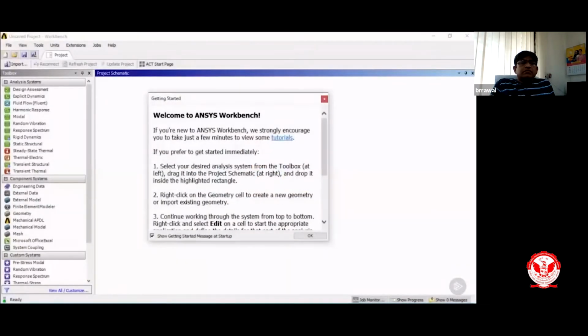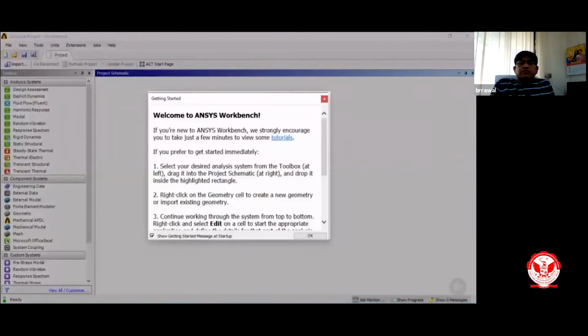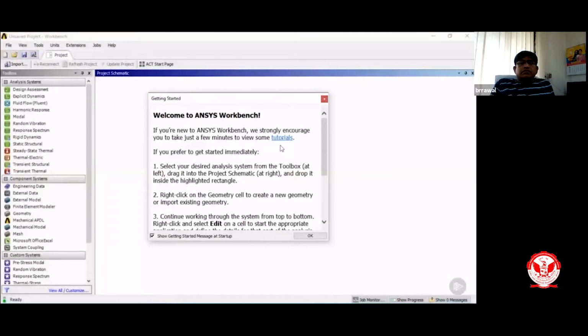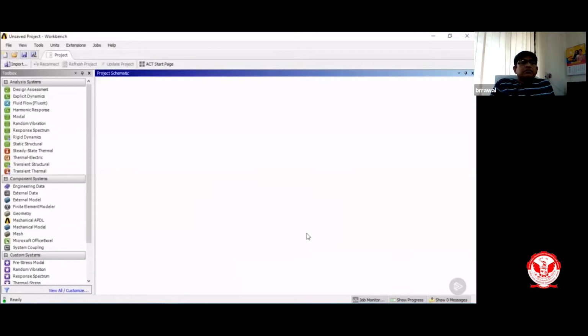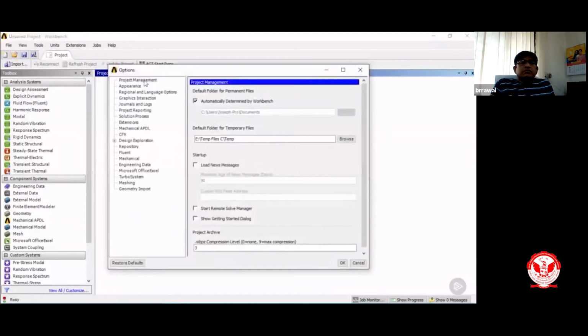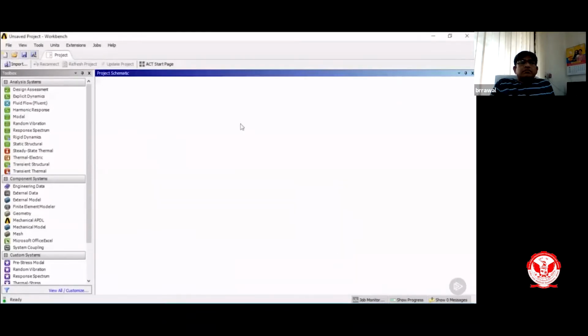Once you open up ANSYS, you'll be presented with a Getting Started page with some useful tips on how to begin a project, as well as a link to some helpful tutorials. I'm just going to go ahead and uncheck this for now and click on OK, because I don't want this pop-up to keep showing up every time I launch ANSYS. If you ever want to bring this page back up, you can go into Tools, Options, and under the Project Management tab, you will see the checkbox for Show Getting Started dialog. You can check that, click on OK, and then every time you restart ANSYS, you'll always get that page back up again.